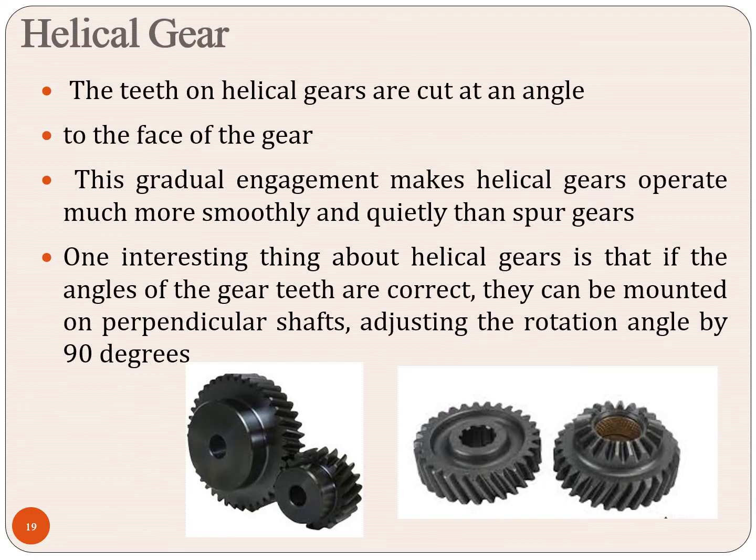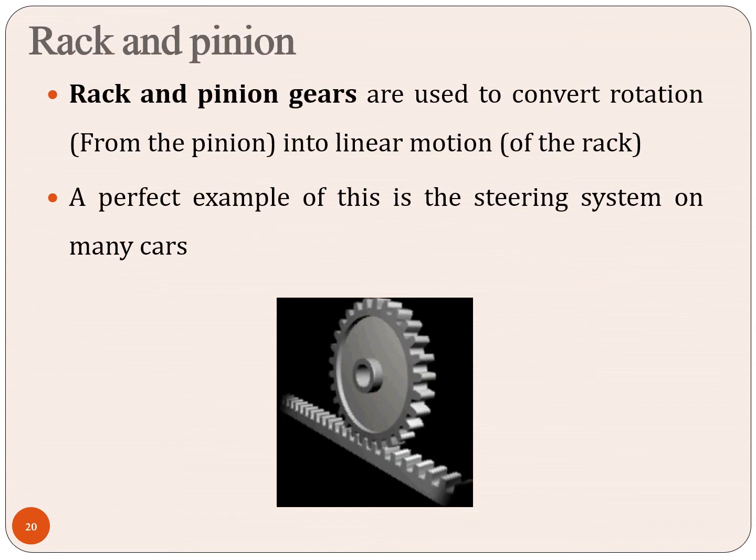This, as I have told, is a helical gear which has inclined teeth. This teeth is inclined, but parallel to each other. This is for power transmission. It is better than a spur gear since the angle of contact and the contact surface is more in the case of a helical gear. This is a rack and pinion arrangement to convert the rotary motion into linear motion.